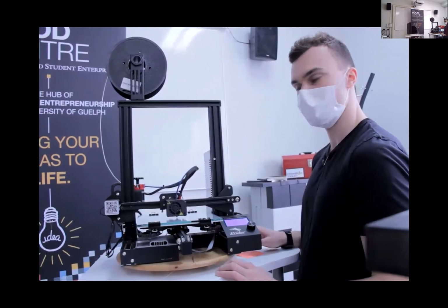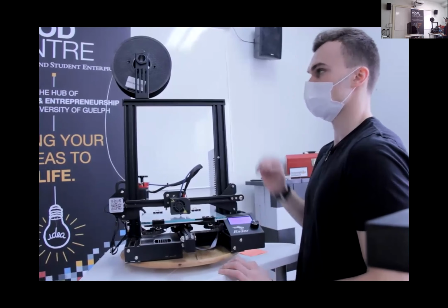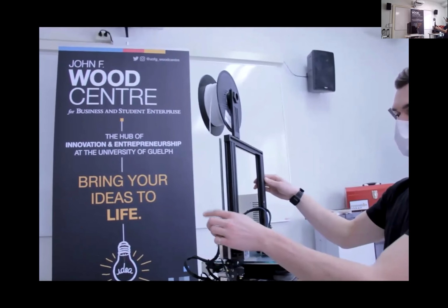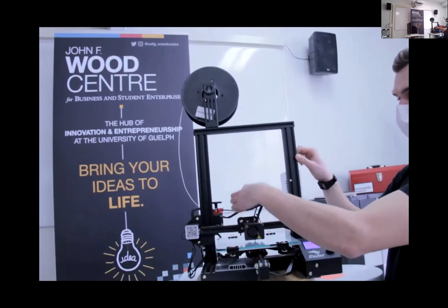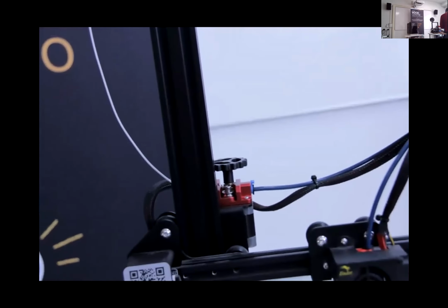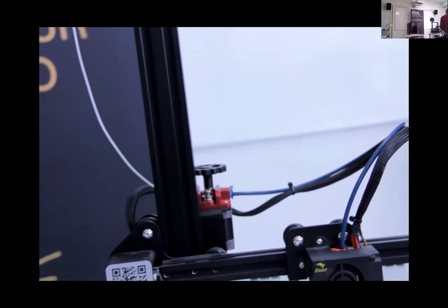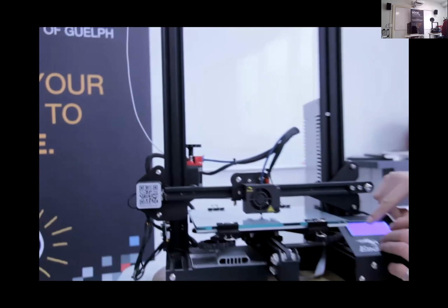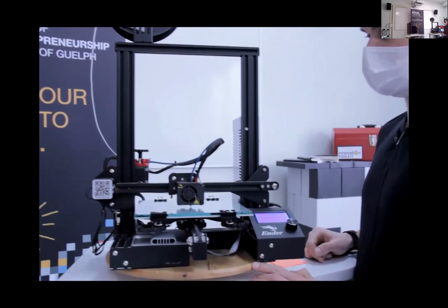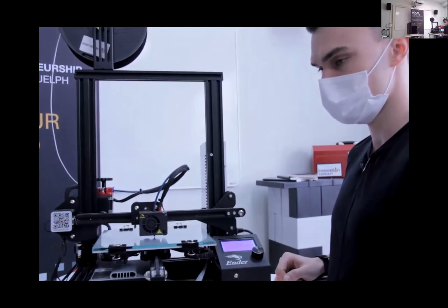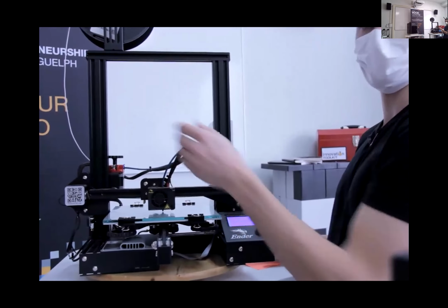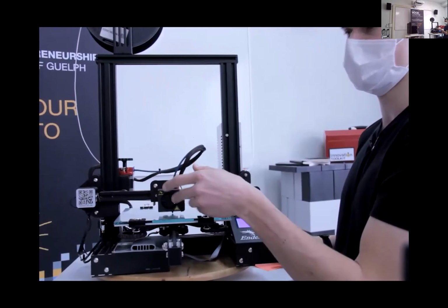So we've leveled our bed and we're preheating the nozzle, the hot end. Let's talk about loading and unloading filament now. So right now there's already a roll of filament loaded and it's running through our extrusion motor into our hot end through this Bowden tube. Okay. Let's check out our temperature. Okay, we're getting up there, 175, 177. So once it gets to about 200, that's hot enough that I can remove my filament.